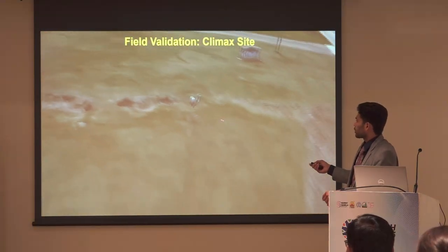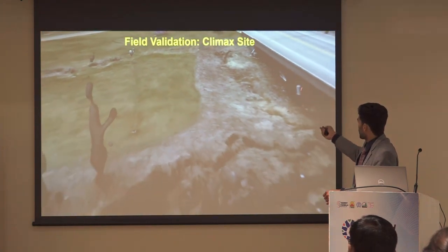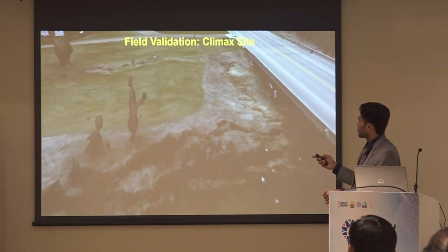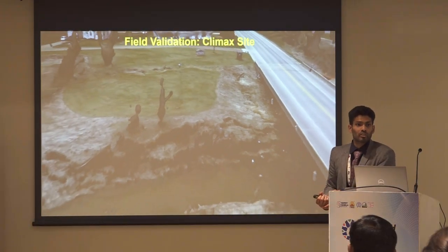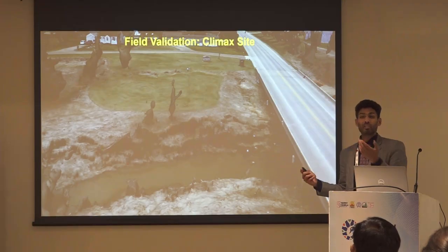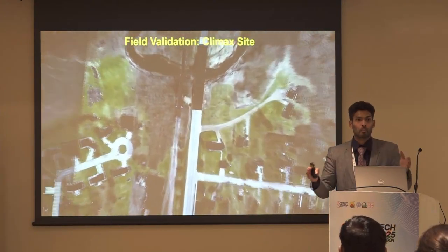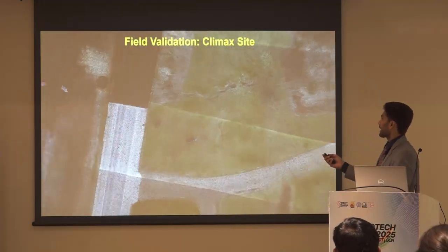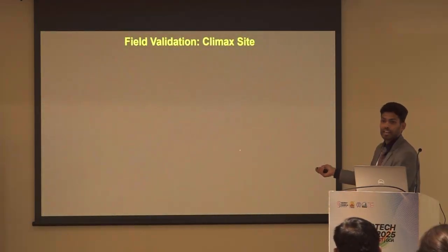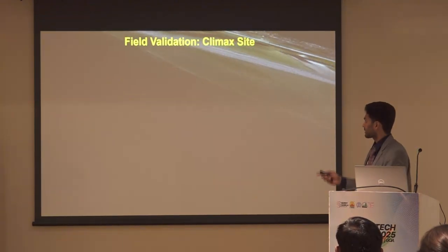And we are using this to do the slope stability. You can see the bridge pier somewhere here. So it's actually tipping. So that's one reason we got a project with Minnesota Department of Transportation where we are doing the slope stability analysis. But when we do slope stability analysis, as you are familiar, we need to use the bare earth point cloud. How do we get it? From the LiDAR. As you can see, this is LiDAR point cloud, which we'll use to get the bare earth and do the stability analysis.